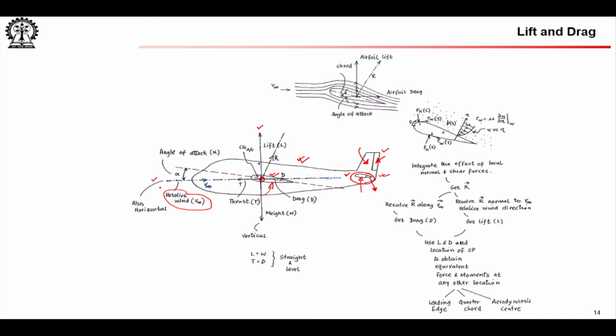So, you can ignore the small velocity of wind that is in the ambient, because the velocity of the vehicle is sometimes orders of magnitude larger than the fluctuations in velocity in the ambient atmosphere. So, if you think of this, this is your relative wind. In this particular case my relative wind is aligning with the horizontal. It is not necessary that they align like that.